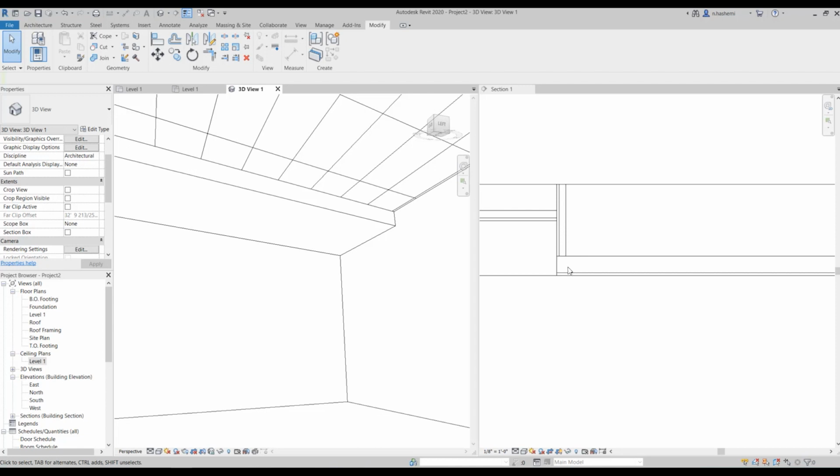Now I'm going to adjust these layers a little bit from the type properties. We have joined these two. What joins actually do is that it joins the core or structure of the walls. And the structure of this one is, let me go to edit type.